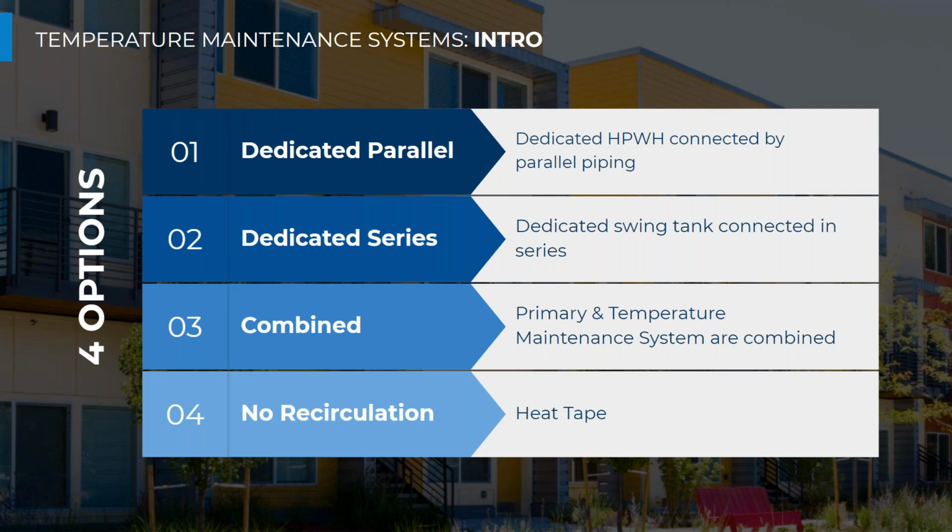And then we're going to discuss a combined system. So what happens when we take the hot water circulation back to the primary storage? We're not going to have a dedicated temperature maintenance system in this example. Everything's combined, both those heat pumps and the storage in that regard.